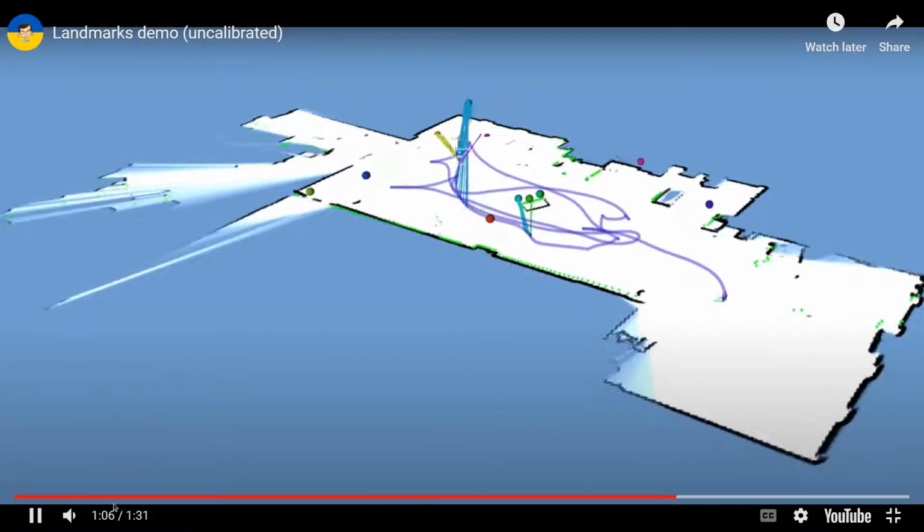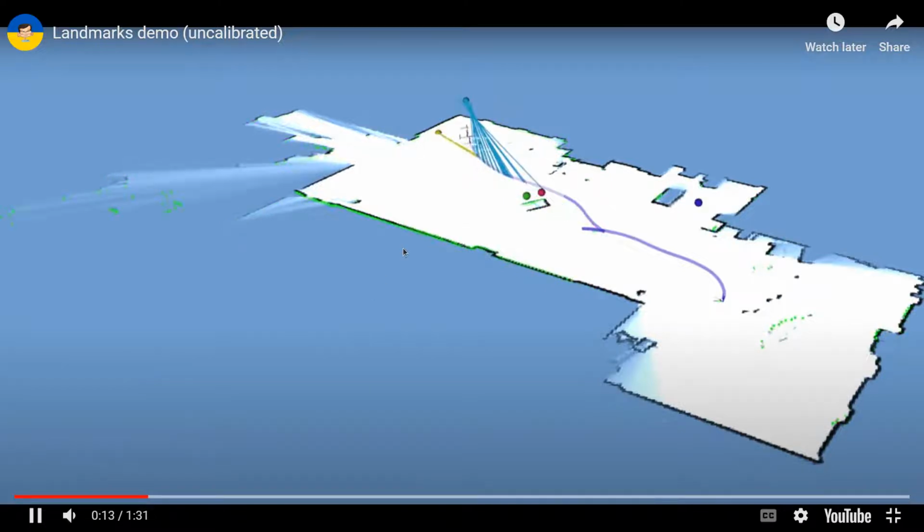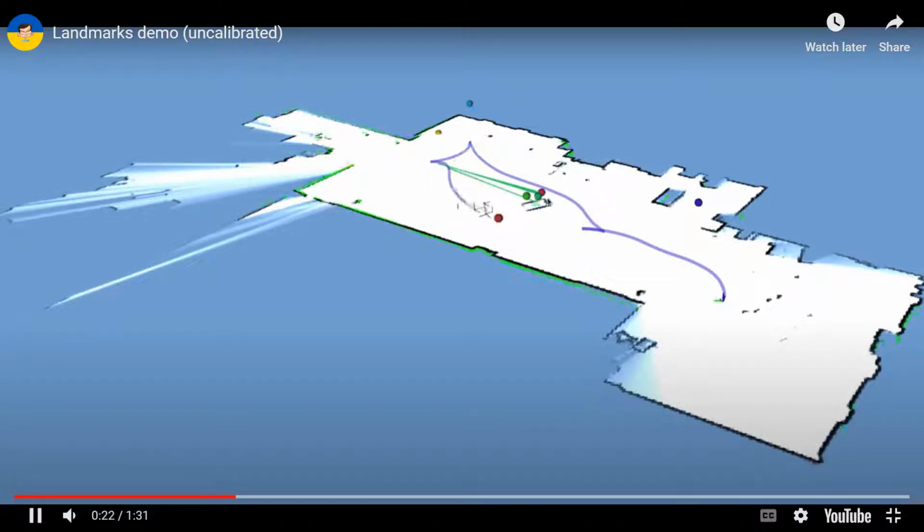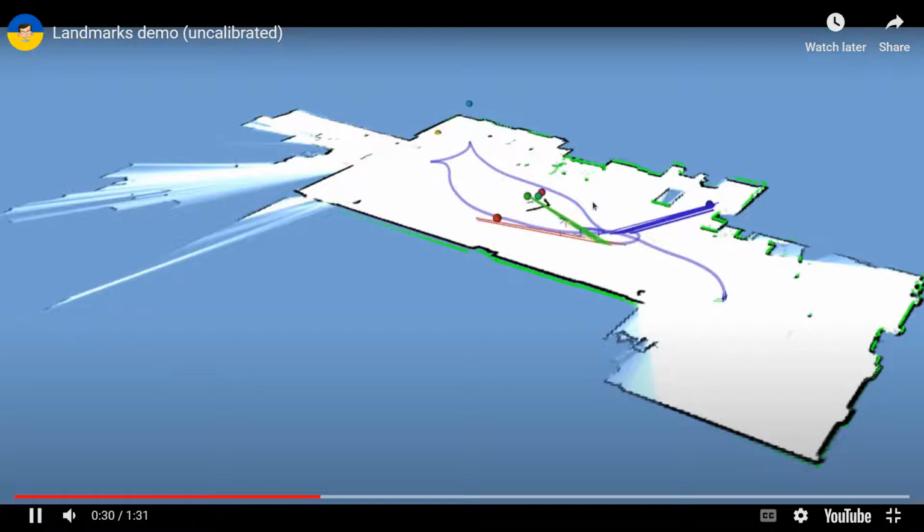These bag files, I think, were not recorded using manual joystick control. It's actually recorded using an exploratory algorithm. So what's happening is that you just start the robot, start the exploratory algorithm, then it will autonomously move around the environment and create the map. So you can see these spheres, right? These spheres seem like the goal positions. The robot will move to this goal position, and then it will get another random position, and then go to that position.